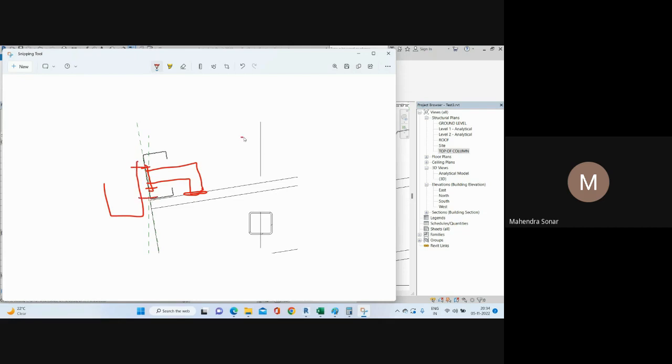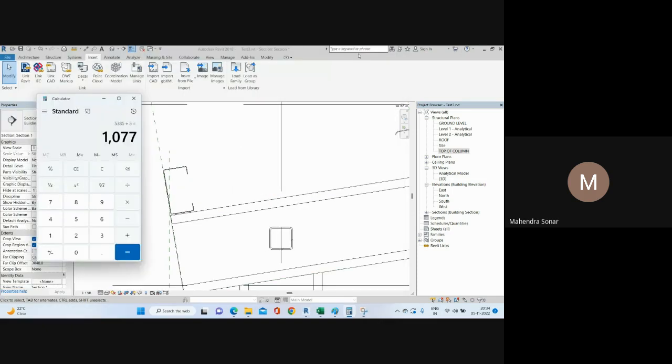Okay, and then the Z purlin, I have explained previously already. So this plate is welded to the top of the rafter. In other regions, except India, people mostly do the welding process in fabrication, not on site, because the site is very far from the city and welding is not possible there.